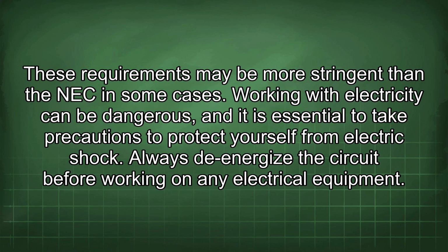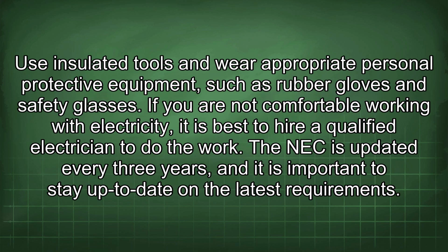Working with electricity can be dangerous, and it is essential to take precautions to protect yourself from electric shock. Always de-energize the circuit before working on any electrical equipment. Use insulated tools and wear appropriate personal protective equipment, such as rubber gloves and safety glasses. If you are not comfortable working with electricity, it is best to hire a qualified electrician to do the work.